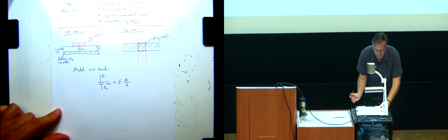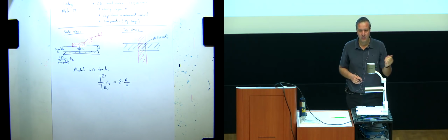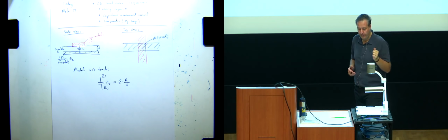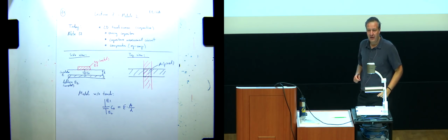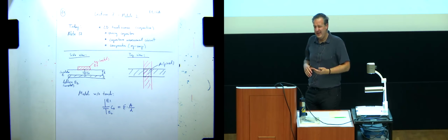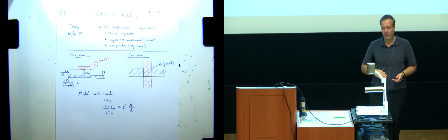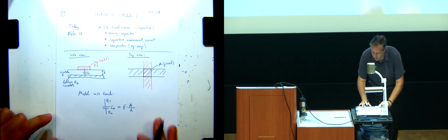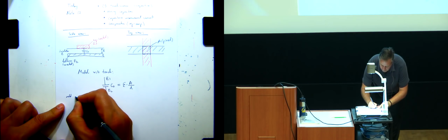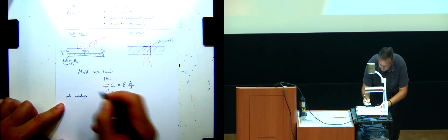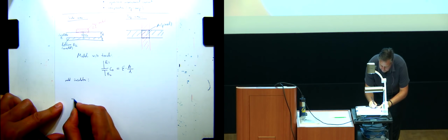So this is basically a case with no finger, right? Just the screen and so on. But now if we want to add the finger, we don't really want to directly add the finger to this picture touching this electrode 1, because we don't want to get zapped or anything. We don't want to have anything with voltages or currents on the phone. We want to be isolated from that with a nice, smooth surface. So what we're actually going to do is add another insulator. And so our picture is now going to look something like this.